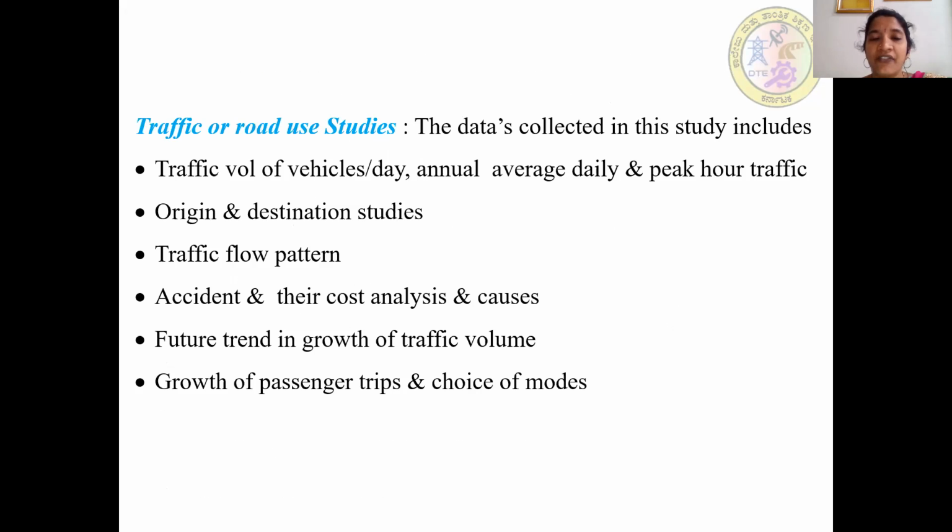Next study is traffic or road use studies. The data collected in this study include traffic volume of vehicles per day, annual average daily and peak hour traffic, origin and destination studies, traffic flow pattern, accident and their cost analysis and causes of accidents, future trend in growth of traffic volume, next growth of passenger trips and choice of modes.